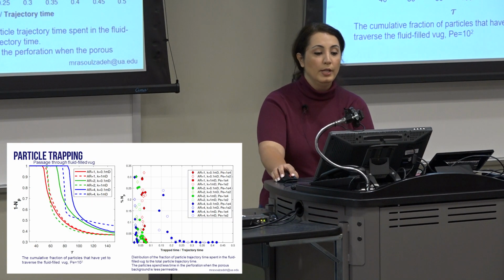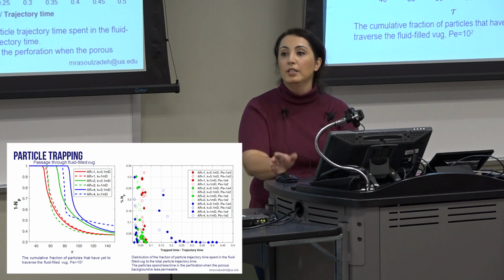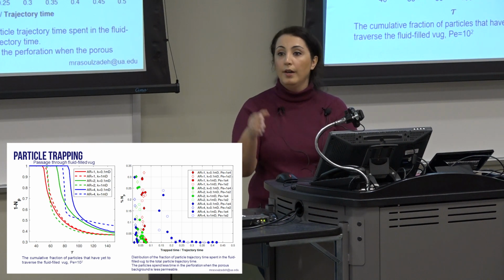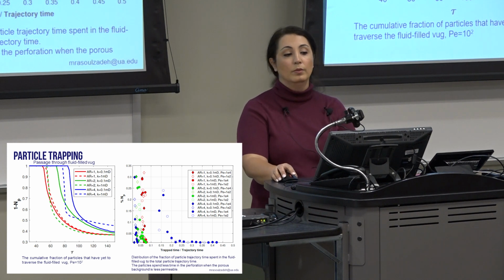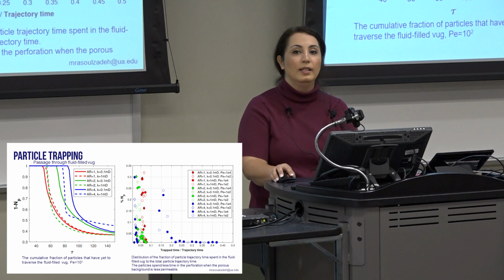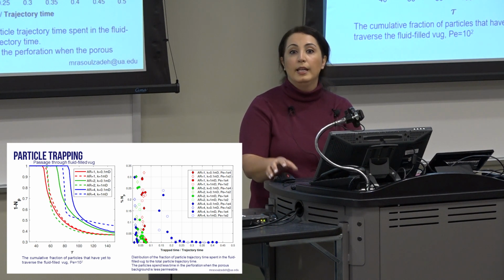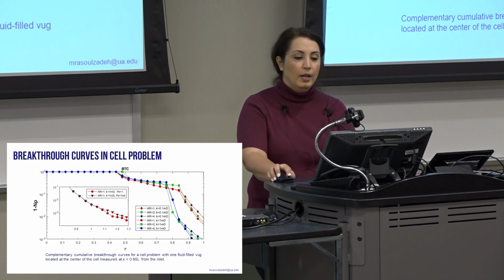We also noticed that in the cases we looked into, about 40% of the particles never make it through the perforation. They go other ways in the medium. This is important information in terms of water treatment or design of filters for water treatment. We also noticed that most of the particles spend less than 10% of their time in the perforations, and they spend most of their time out of the perforation.